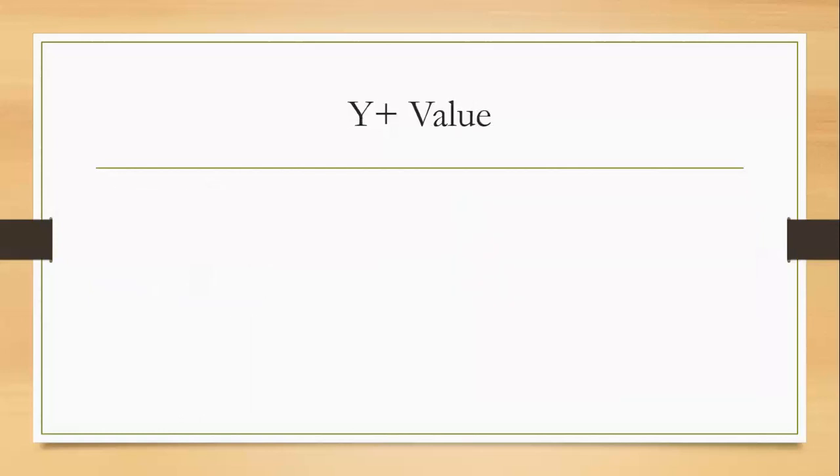Before we move on to the turbulence model, we must discuss the y plus value. Y plus is such a vast topic that just to cover it, I may need an extra class, but for today's session I will keep it very short. The y plus value is used for turbulence models only. In laminar flow, you won't need this y plus value. It is needed only in turbulent flow, wherever we are concerned with the boundary layer.